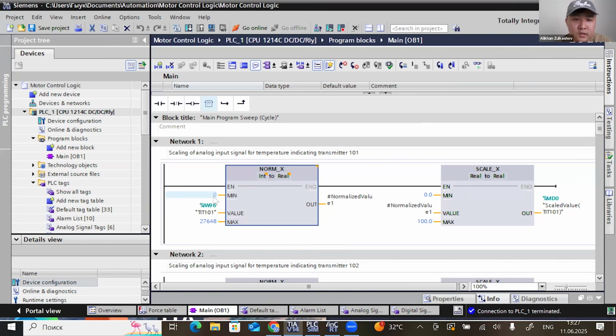It is just the normal operating range, particularly for Siemens software. We also have low saturation, upper saturation, low range value saturation, upper range value saturation. We also have bad PV, bad process variable, which comes for example if we have a short circuit or an open circuit.